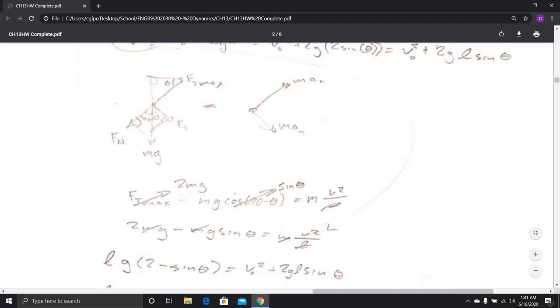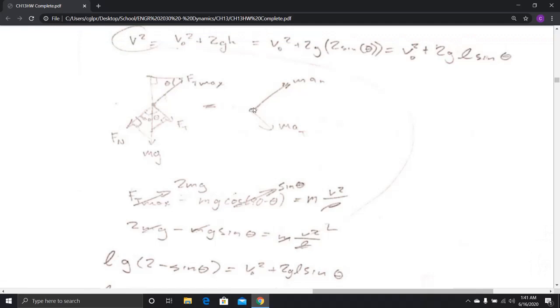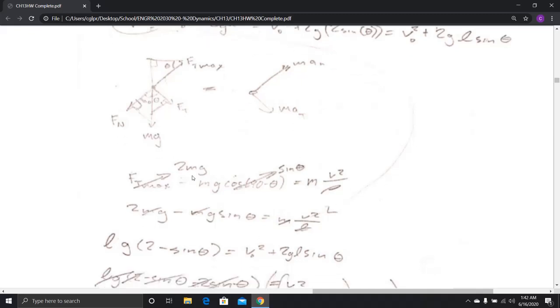realizing that I'm wanting to look at how much force is going to be applied to the rope, and that that amount of force is going to be the maximum force of tension minus the normal force of the weight of the sphere, since these are going to be acting in opposite directions. So I create that relationship, and I know that it's going to be equal to mass times the normal acceleration, which is v squared over rho, in this case L.